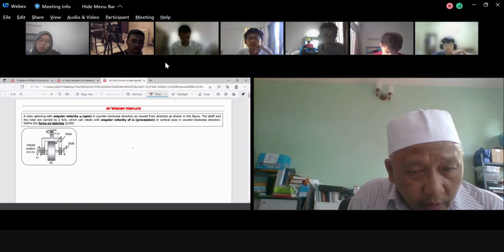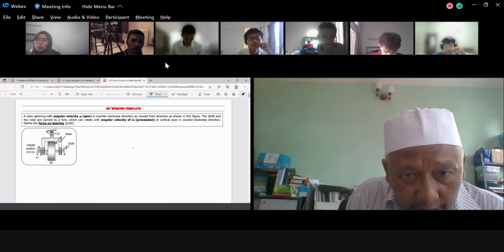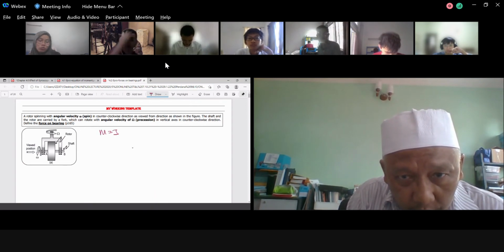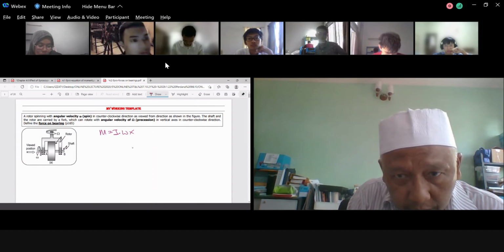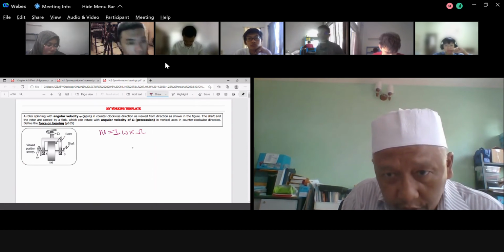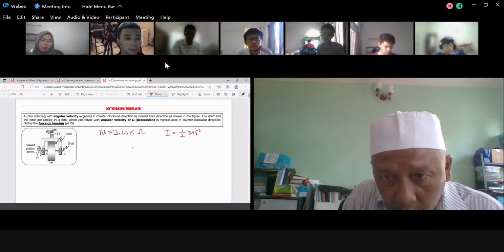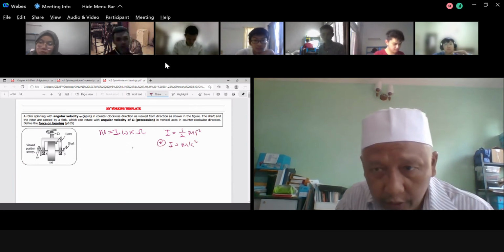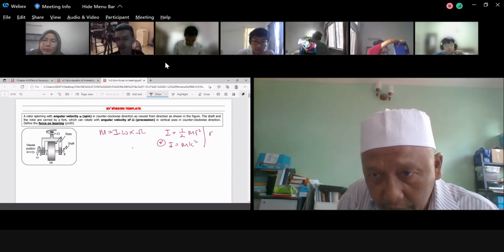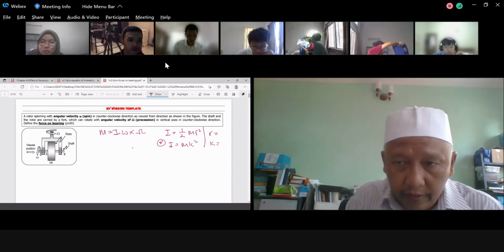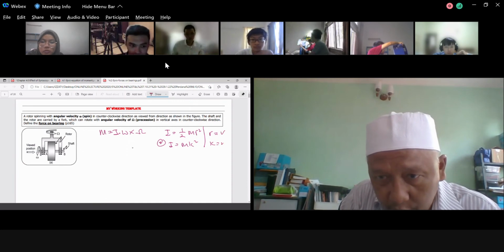Okay, first is what we had just now: M equals I omega cross precession. I can be from m r squared, or I can also be equal to m k squared, depending on whether r or k is given. If this one is given or this one is given, use each one accordingly.